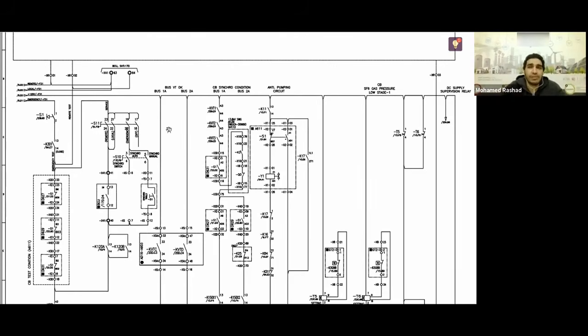There is no difference. But the only benefit is that the PCU will handle the synchronization process more or less. However, if you are using the emergency mode, you will just bring a trolley and look at its synchroscope. Sometimes you have a synchroscope available inside each LCC. Of course, it's just a mode of operation, nothing more, nothing less. But if you're talking to me about the PCU, you need to choose the local mode, which means you will close it via the PCU. This means you must be present at the station and standing in front of your cell, of course.